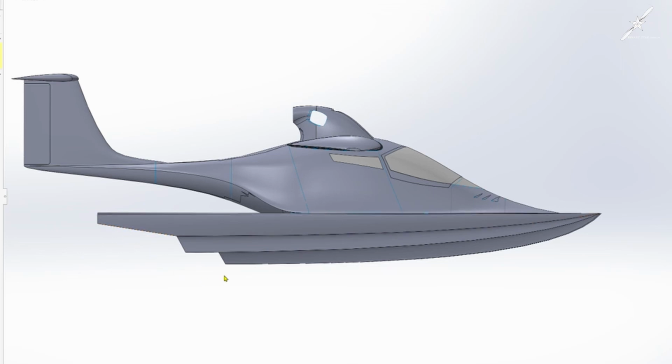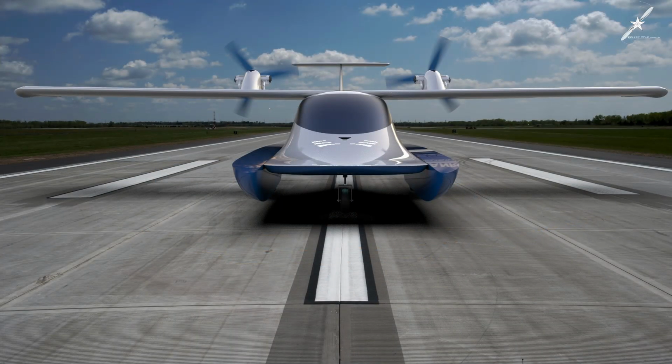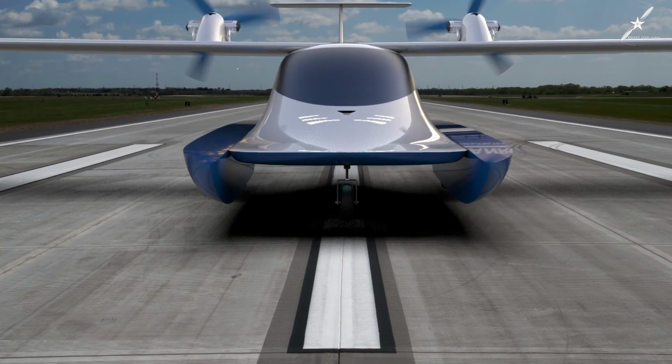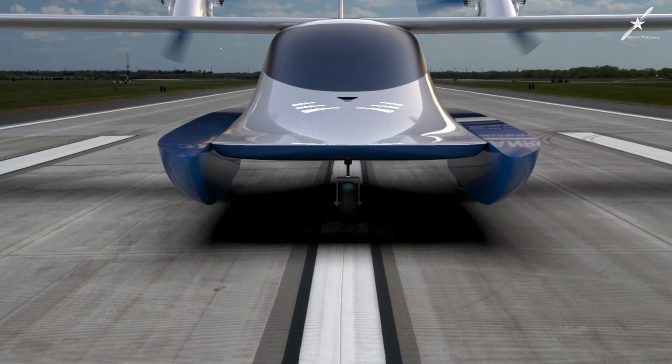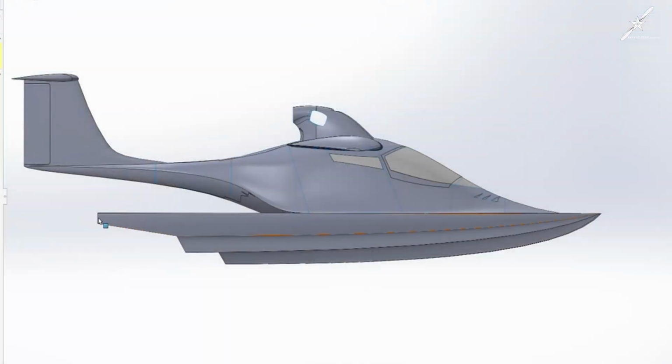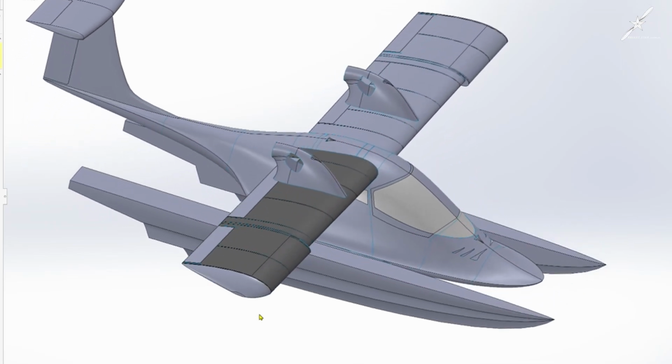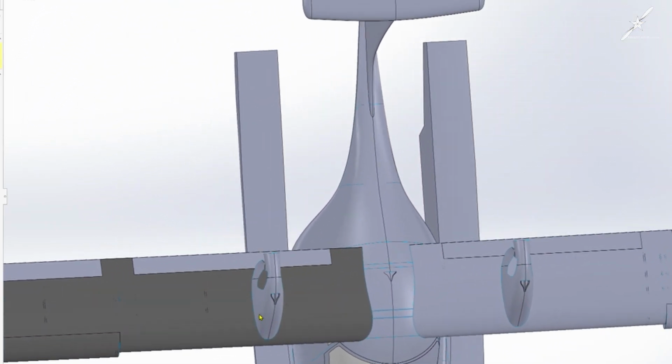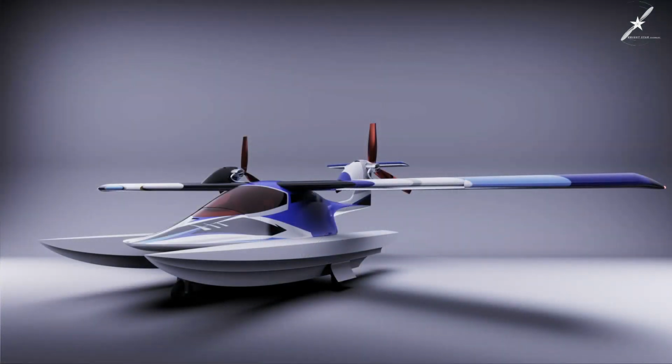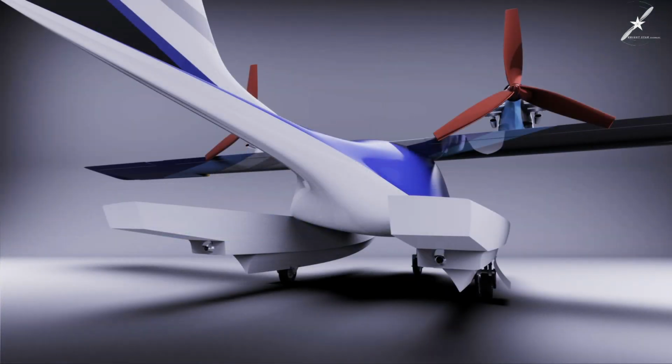Originally, I was going with a speedboat shape as I figured it would allow us to cut through the water faster. But then I got to thinking, this shape may be this way to help the boat stick to the water, and that's just the opposite of what we need. What we need is a planing hull to get the aircraft up and out of the water fast. Also, on landing, I don't want it to sink into the water like a knife's edge. So the shape of the pontoon has gone through a lot of changes this last year. Here's the most recent shape we have basically settled on.